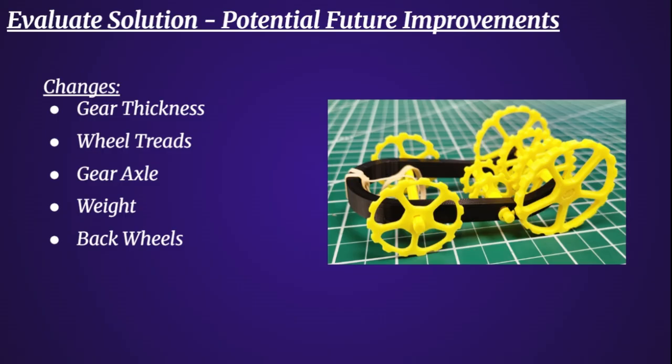Moving forward, my gear axles shift back and forward and require two C-clips to hold in place. If I had changed the shape of the axle, I could have definitely made the C-clips obsolete in the design. Making the keys thicker would have possibly made this harder for the gear's axle to shift. Another positive change would have been the wear reduction in the body of the vehicle.